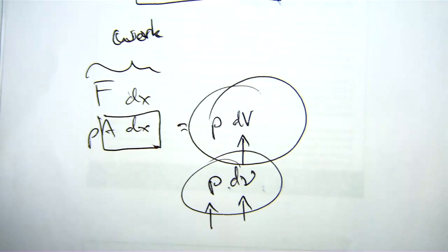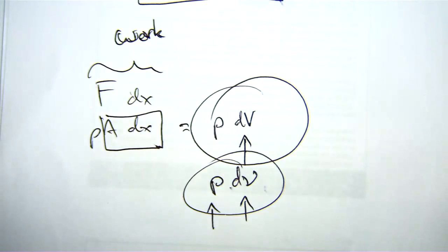Expressing it in terms of area doesn't actually help me in determining the state of the system, and I can't divide area by mass and say my area per unit mass. These are not things that define the working fluid. But the specific volume of the working fluid and the pressure define the energy inside that system, which means now I have a way to express the work done that is in the same language as how I think about energy. So even though it looks like a trivial change of units or change of integratable variable, we do it because our life gets easier having done that swap.